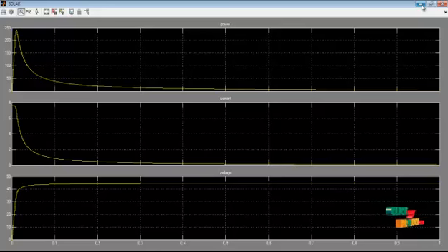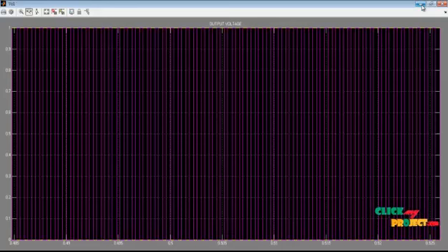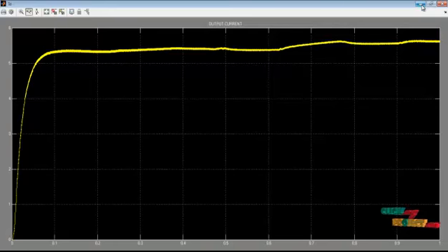Next we see the pulse waveform, generated in the PWM generator using the MPPT technique and the controller process. This is the pulse waveform, generated in each division from the duty ratio of the MPPT. And next one is the output current waveform. Initially there is a rise time, and after the rise time the voltage or current becomes constant. Here the output load is 5 ohms, and this is the output voltage waveform.